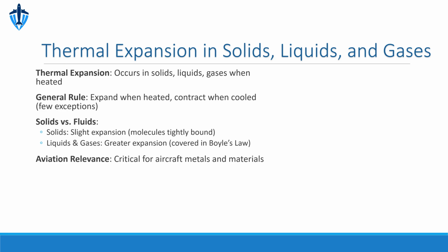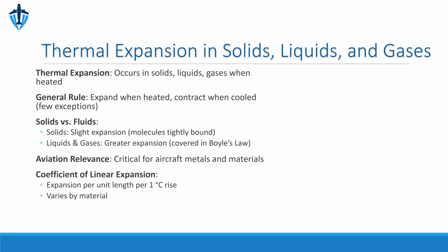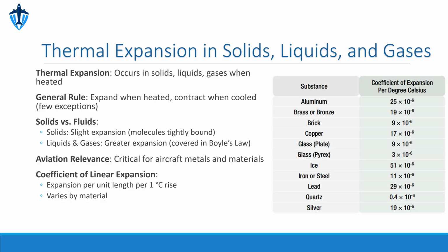Each material expands at a unique rate, measured as its coefficient of linear expansion, listed in this figure. To calculate expansion, use change in length equals coefficient times original length times temperature rise. This simple formula is essential for predicting material behavior under heat.